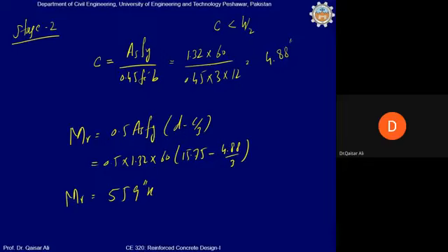You can see that this value is greater than the capacity corresponding to stage 1. And this is quite logical because at that stage you are not allowing even cracks in the beam, and in this case you are utilizing half the material strength. Clear?